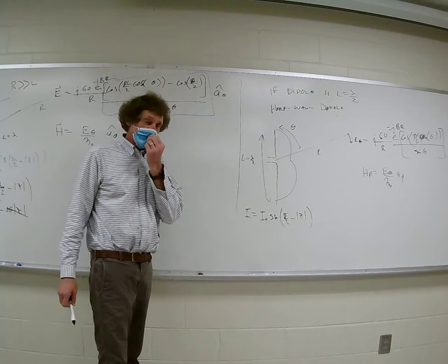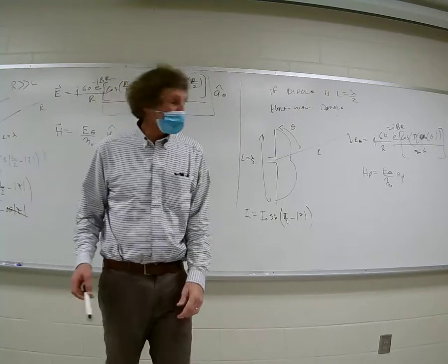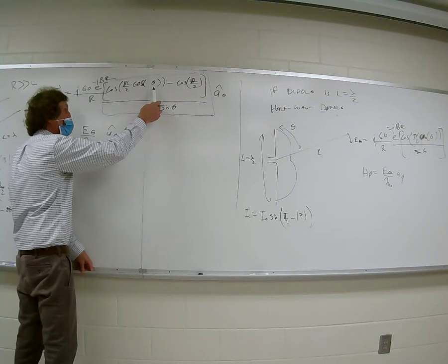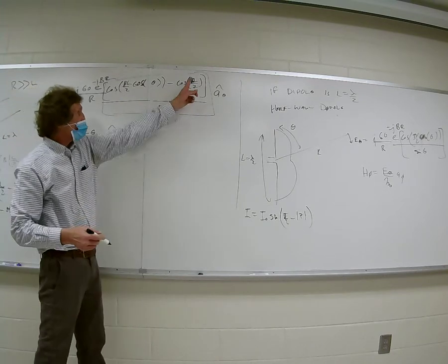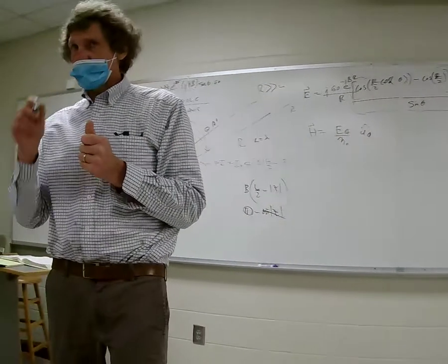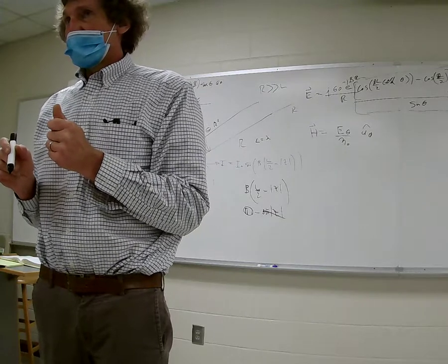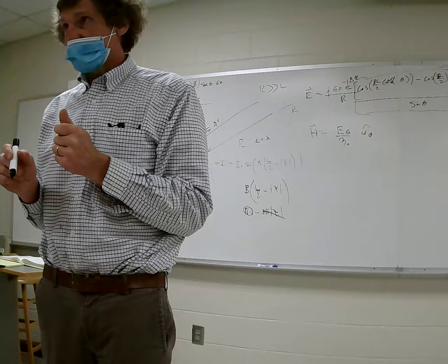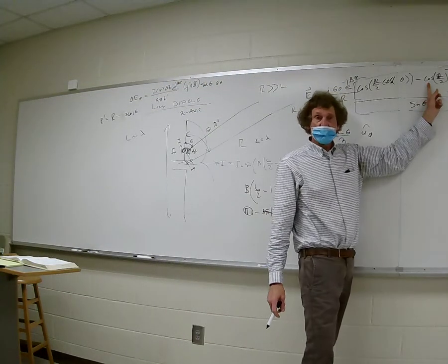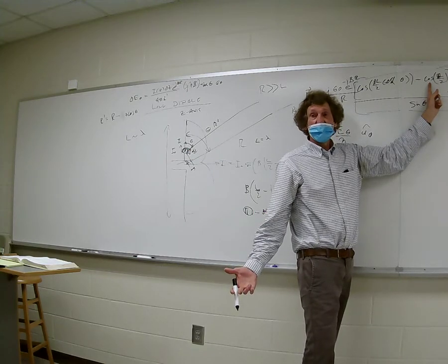Now, that's not really true, but let me go through that. If the dipole is a half-wavelength, when I look at this term right here, this is the formula for the electric field from an arbitrarily long one. That's beta L over 2, right? Well, beta is 2 pi over lambda, and L is lambda over 2, so the lambdas cancel, and I get pi over 2, wouldn't I? Well, what's the cosine of pi over 2, a cosine of 90 degrees? It's 0, isn't it? This goes away.